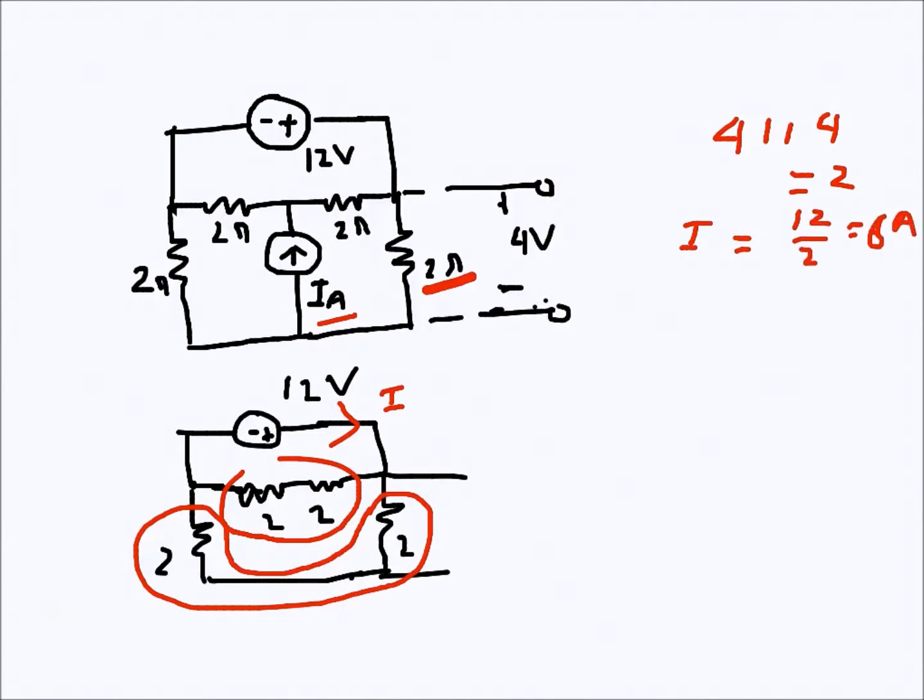And since these parallel paths are of equal resistances, it will be just divided by half. So the current through this one, which we are interested in, is 3 amperes. So the voltage drop due to this one will be 6 volts, just for the voltage source. The voltage drop in this resistance will be 6 volts in this direction, but it is given that the voltage drop in this direction is actually 4 volts.